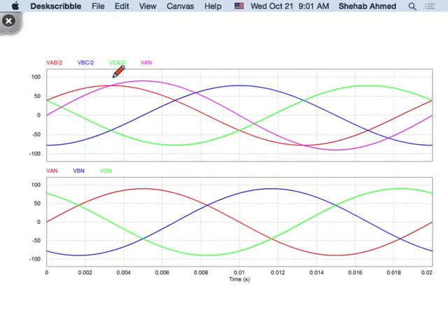The output voltage on my load will sometimes be the input phase voltage, which is VAN, if I have all three diodes on, or it will be the line voltage divided by 2, because I've taken my line voltage and applied it to 2 equal resistors and chopped that in half, right? So that's the reason why I went to that discussion.